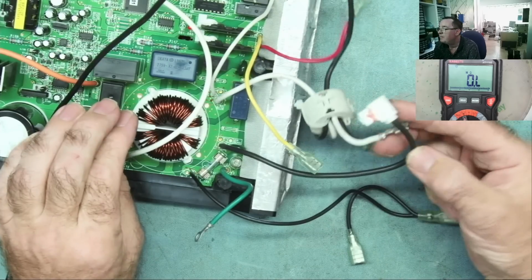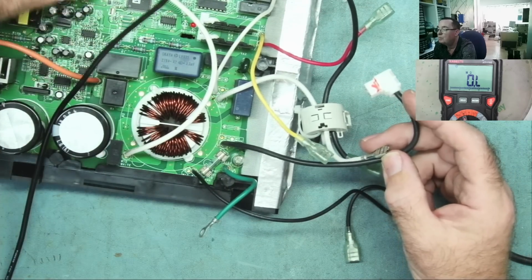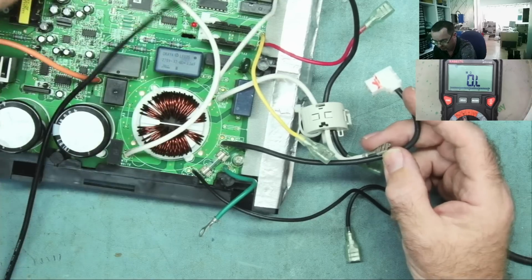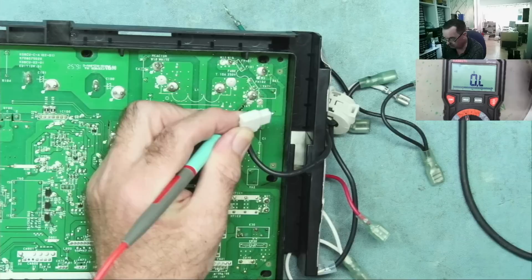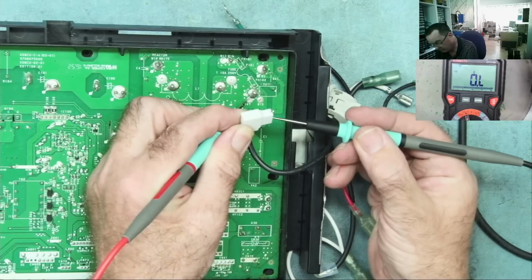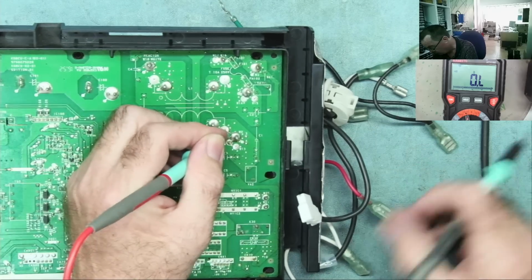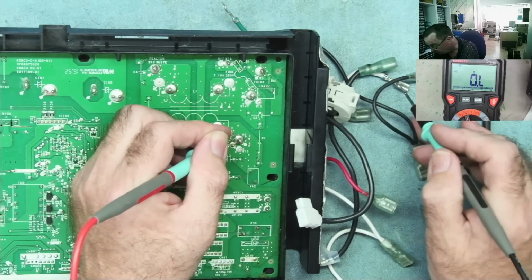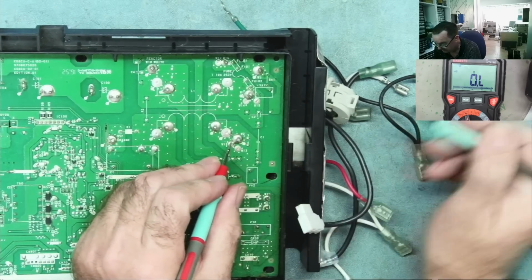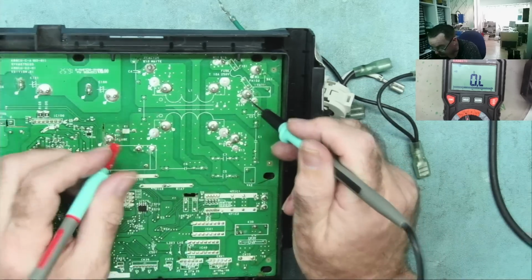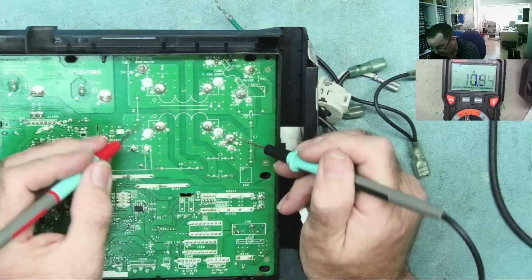So this is where the power comes in. We can see the black and the white wire. This is a big double inductor basically filtering. So power in there, that's one of them. Power into the other one, I think it's this white one. Yes, that's where the power comes in. We can connect our mains here, no problem. Then this one goes through an inductor, same with this one.